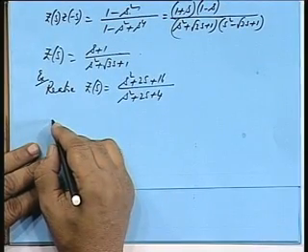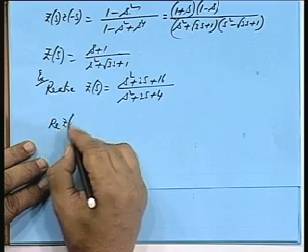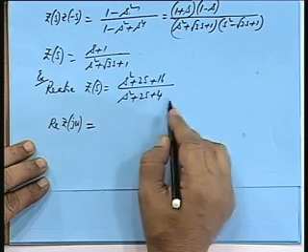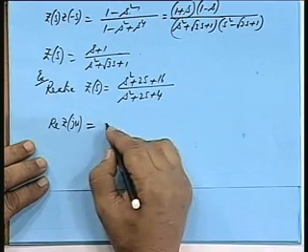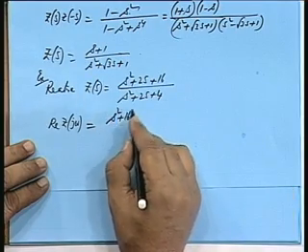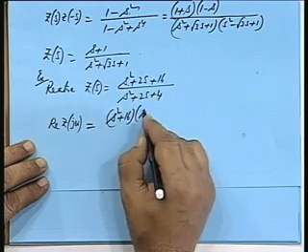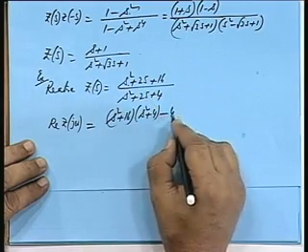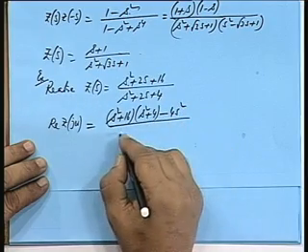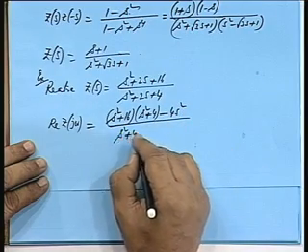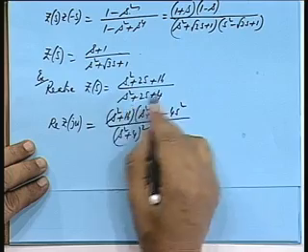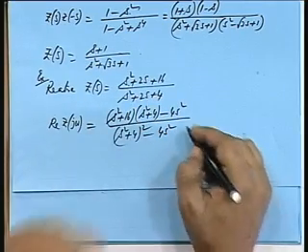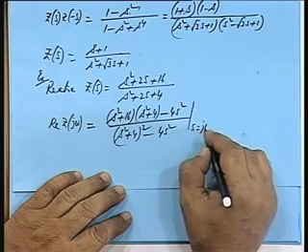So what was the starting point? The real Z j omega we compute, that is (m1 m2 minus n1 n2) by (m2 squared minus n2 squared). So (s squared plus 16) even part into (s squared plus 4) minus 2s into 2s, 4s squared, divided by (s squared plus 4) whole squared, that is m2 squared minus 4s squared, n2 squared, s equal to j omega.